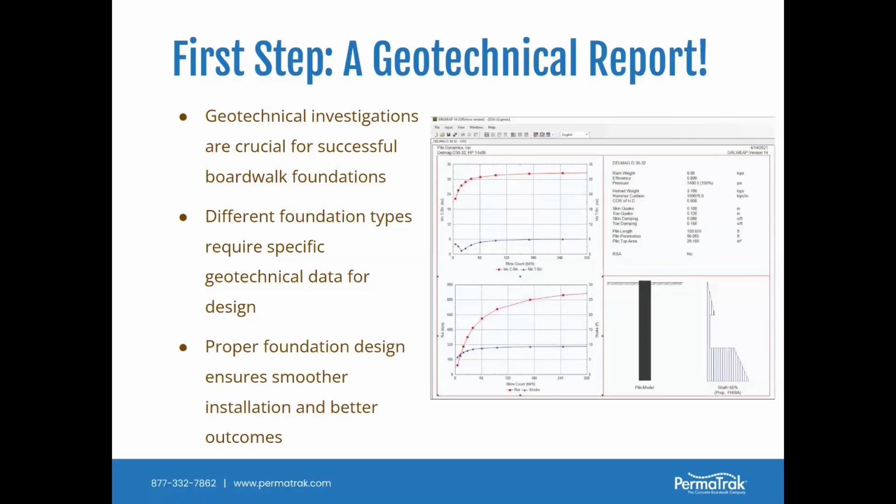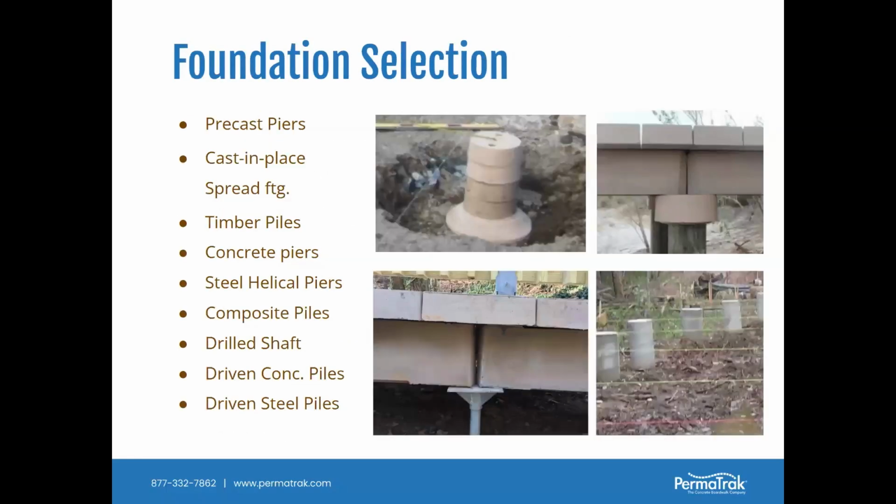So there are definitely foundation types that really don't make a lot of sense for the soils, based on what the geotechnical engineer says in the report. Without a geotechnical report, you're simply guessing on what the foundation type should be. And it certainly just provides for a smoother process from beginning to end and helps protect your client from excessive change orders down the road and delays.